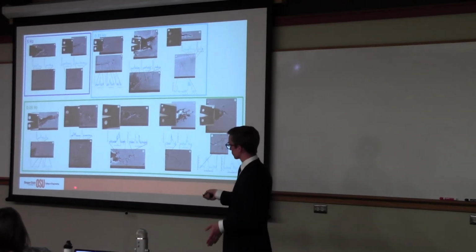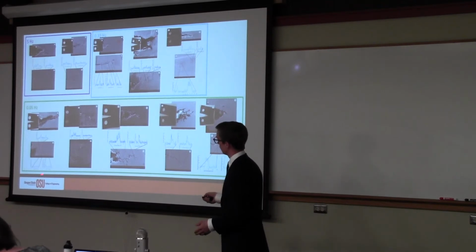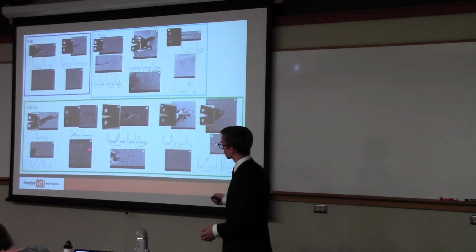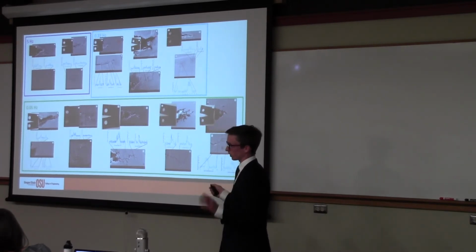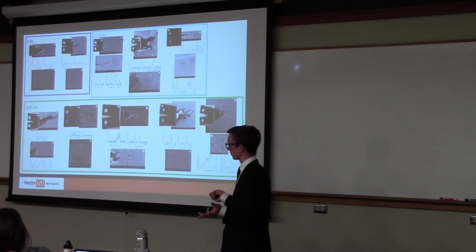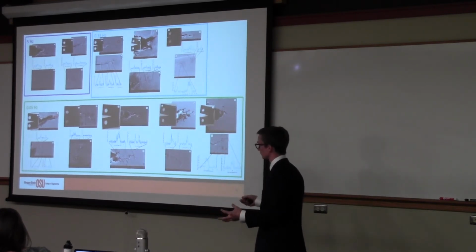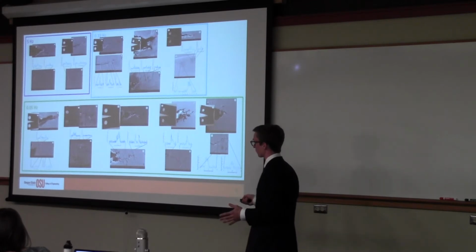And when you slow it down to 0.05 hertz, something interesting actually happens that is worth talking about for just a second, which is that these 2 pictures here are the low delta K tests of a 0.05 hertz waveform, and when we chop it and look at the profile, what we see is a protective oxide forming behind the sharp crack tip.